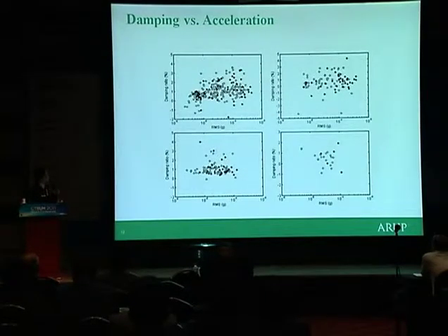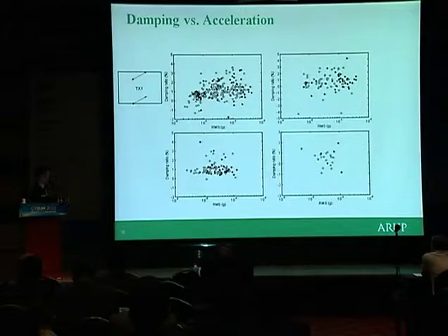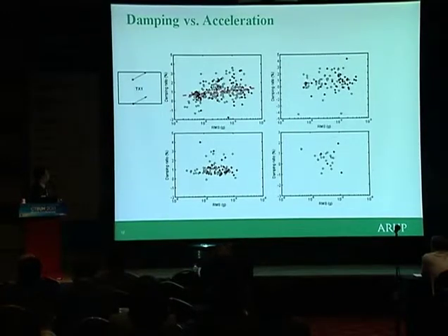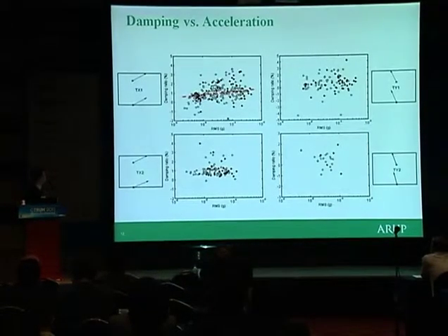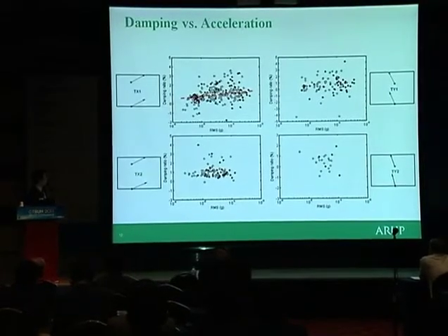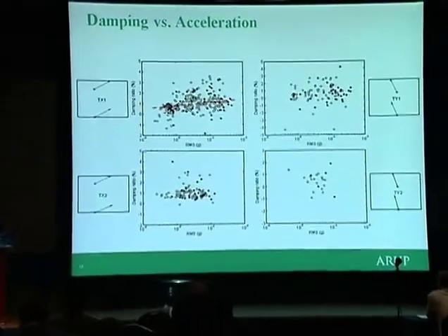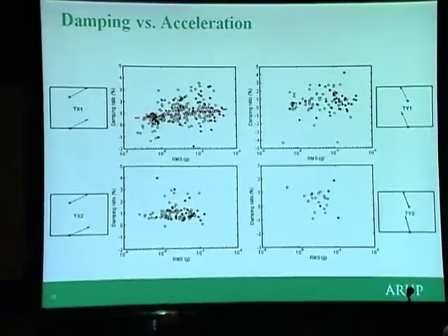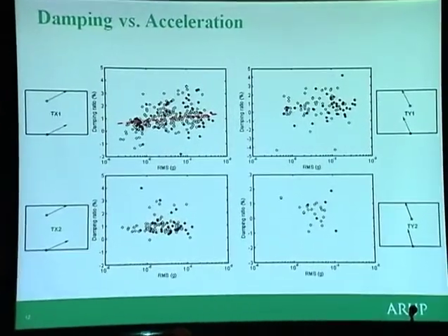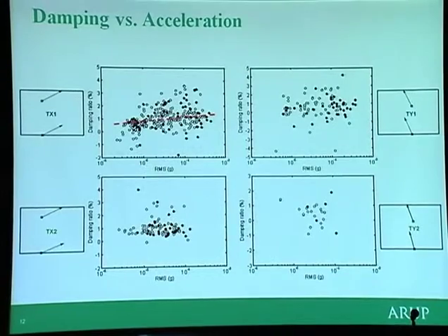That shows the damping ratio versus the acceleration for that building in those two typhoons. So the y-axis shows you the damping ratio, and the x-axis shows you the acceleration. If we plot, you can see the scatter of those damping, but if you look at the trend line, there's a slight increase, but we don't know. We need more data to confirm that.